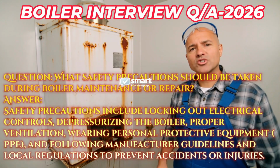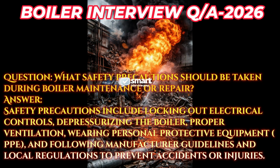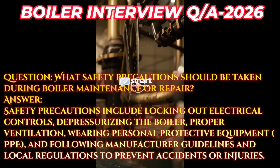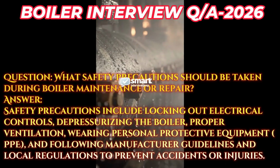Question: what safety precautions should be taken during boiler maintenance or repair? Answer: safety precautions include locking out electrical controls, depressurizing the boiler, proper ventilation, wearing personal protective equipment, PPE, and following manufacturer guidelines and local regulations to prevent accidents or injuries.